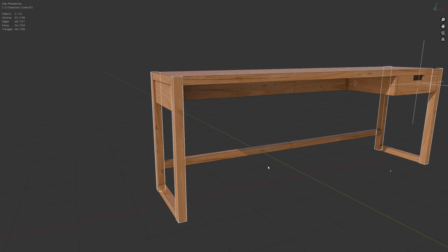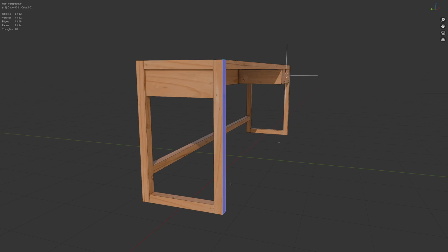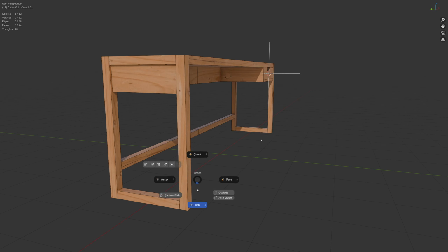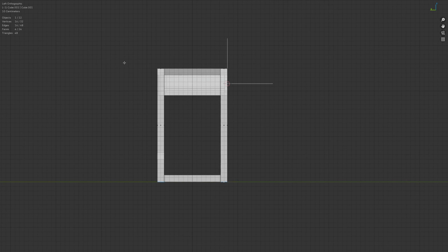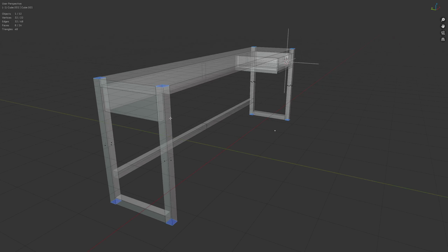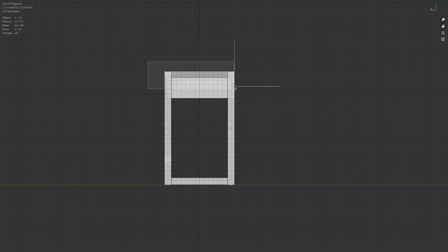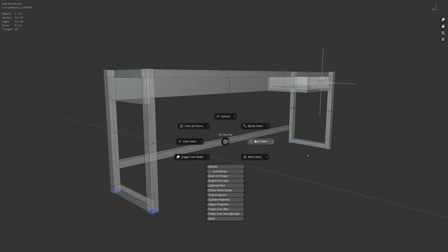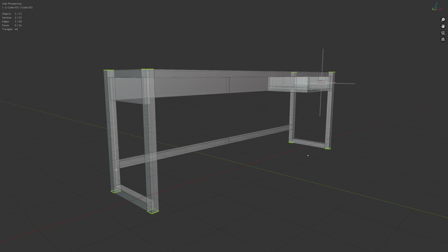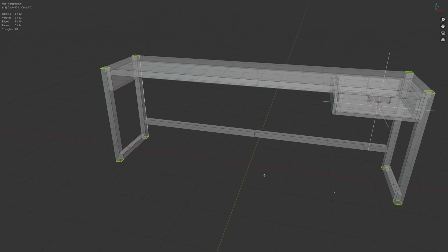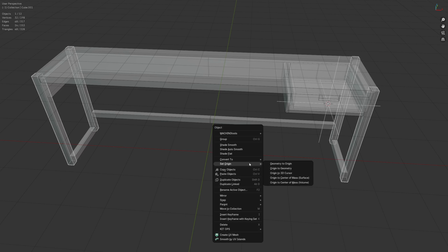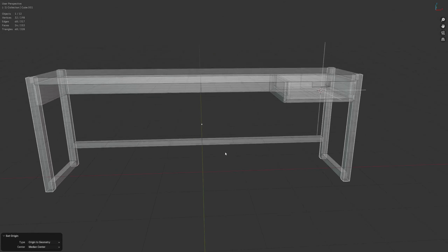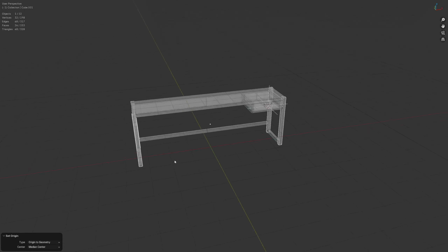The main thing is I got to get working on this because we got a number of seams to add, right? And so all I'm going to do is we'll try doing these in batch. Let's go to solid view. These are all the leg pieces, right? And we'll shift, select, use the select box, shift. We got all those. We just mark them as seams, right? Then we can do a selection here. If this is a symmetrical object, which it is, but the origin point's not in the right spot, so we can right click, set origin to geometry. You'll see it goes to the center.